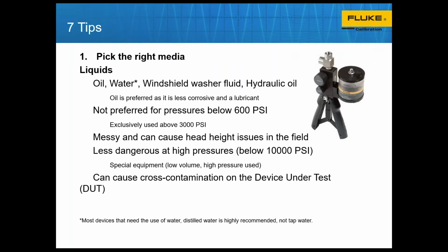First of all, the one at the bottom says cross-contamination. If I was taking an oil pressure hand pump into the field and I was calibrating some other process, and oil in that process didn't mix well together, then I would have a contamination issue. So you just need to pay attention to that part of it. There can be other types of fluids that may be compatible that you might want to switch to, especially if you need to get high pressures.